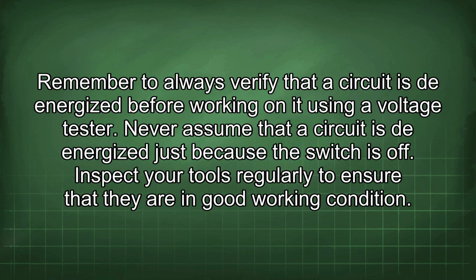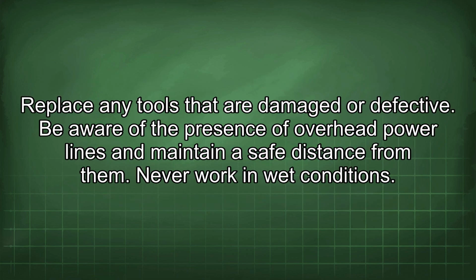Remember to always verify that a circuit is de-energized before working on it using a voltage tester. Never assume that a circuit is de-energized just because the switch is off. Inspect your tools regularly to ensure that they are in good working condition. Replace any tools that are damaged or defective. Be aware of the presence of overhead power lines and maintain a safe distance from them.